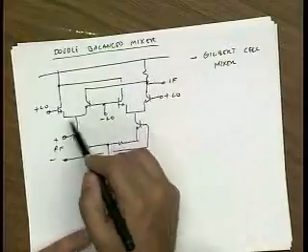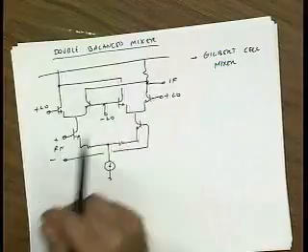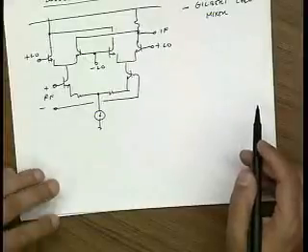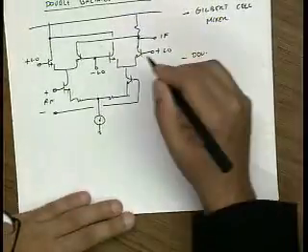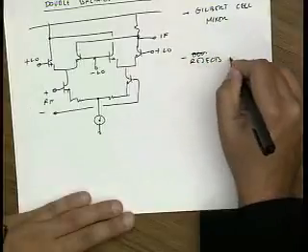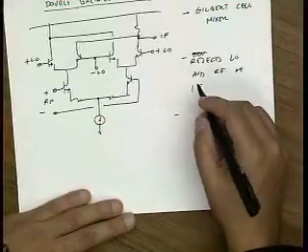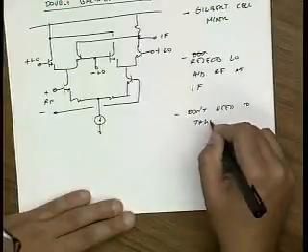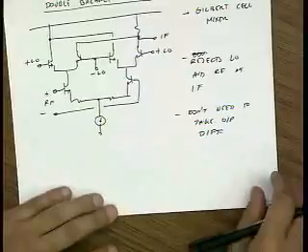But the interesting thing is that we have a second differential pair which is wired up with opposite polarity. So let me actually just draw what the circuit looks like for positive and negative LO. But let me just say a few things before we draw it. Let's say that this is a double balanced mixer. I already said that. That means it rejects LO and RF at IF. And I don't have to take the output differentially. This is stuff that I'm stating, but I'll show you guys in a second. Okay? So let's see how this circuit works.